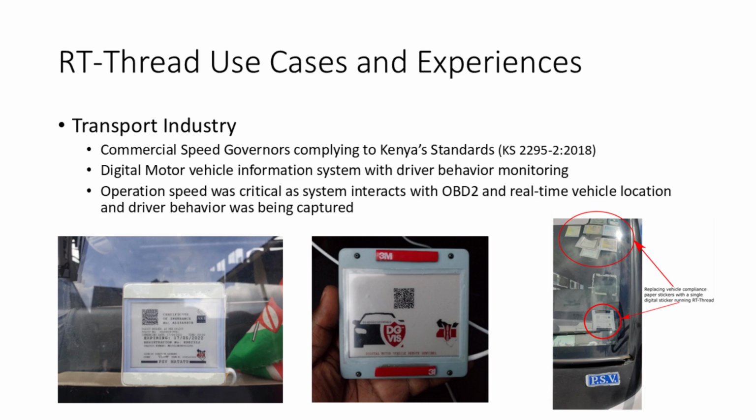For example, if the insurance sticker has been updated, or if the vehicle has been flagged for being in the wrong area, or if an access code has been provided, it will update the screen to display that information. So all these functions, on top of connecting to the vehicle's OBD system and capturing real-time information about the vehicle, required an RTOS that is stable, can operate fast, and has very good networking capabilities. And RT-Thread was the go-to solution.